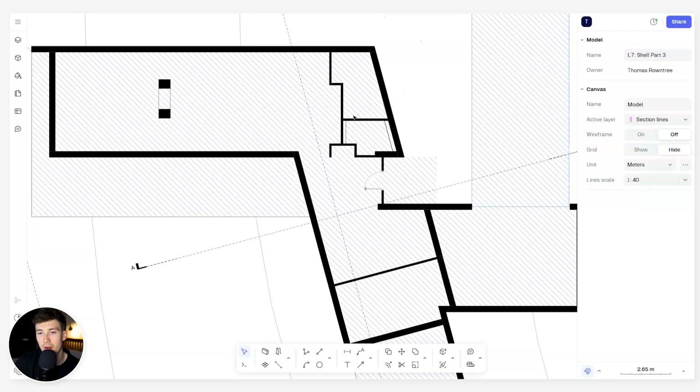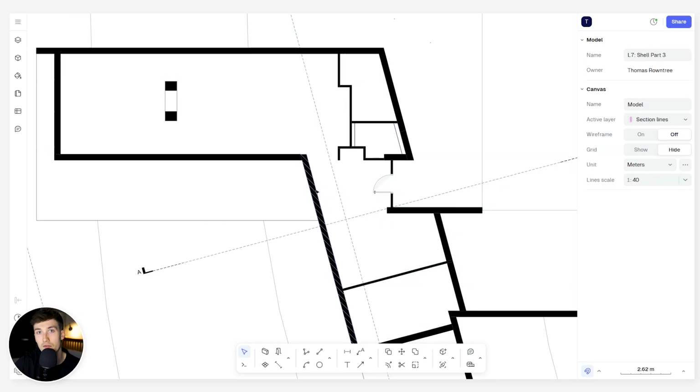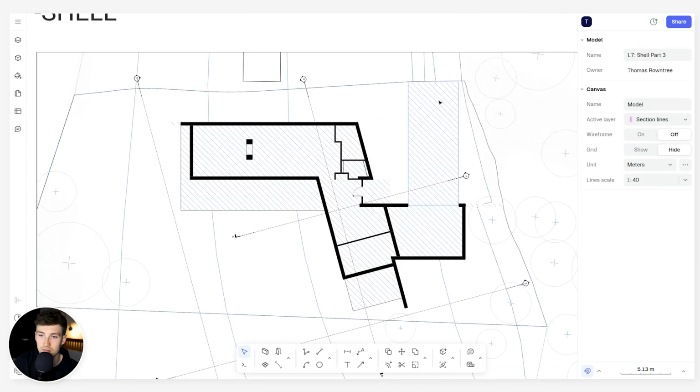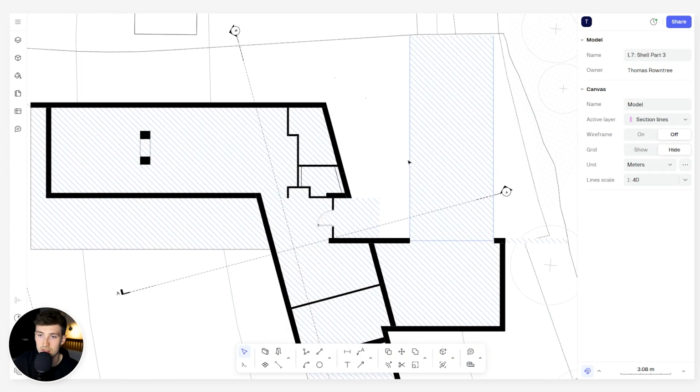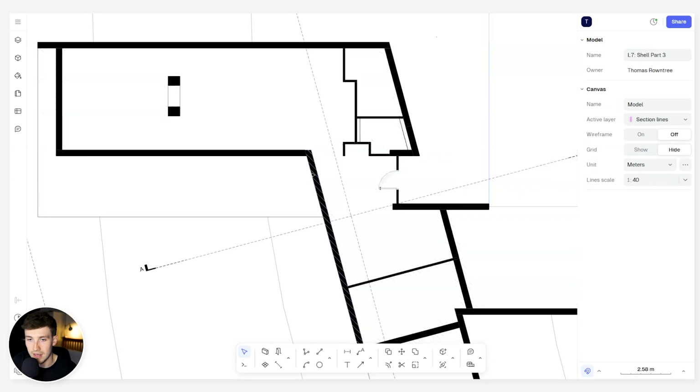Now the way that I want this floor plan to work is, as you enter this opening space, I want this to be an arrival point, as I've mentioned in the previous lessons. I want this to be a point where you obviously have these options of moving in different directions, but you also have this sense of arrival and views over the landscape. So as you enter this back, more public zone where you have the driveway, obviously it's quite a closed area because of the nature of the landscape. But as you enter through the space, I want there to be glazing that opens up these views from the moment that you arrive into the property.